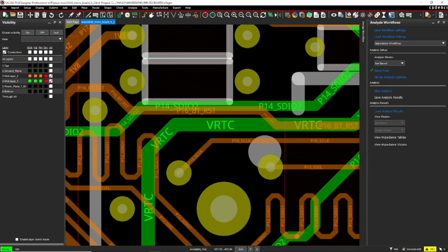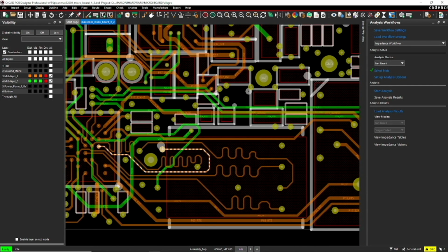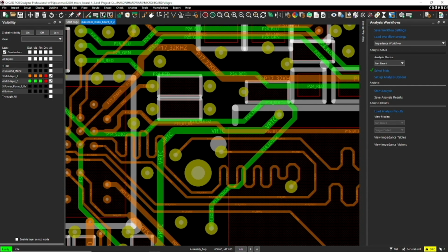All right, there are some signals in layer 3 that have squiggly patterns. And we talked about this for a moment earlier. Why is this? Well, some signals need to go from a transmitter to a receiver within a certain time frame and within a specific time compared to other signal arrival times in order for that receiver chip to understand what's being transmitted.